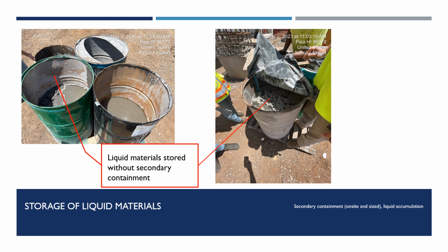Storage of liquid materials requires secondary containment measures to capture any leaks, drips, or potential failures of the container. Secondary containment measures may be plastic prefabricated spill pallets or properly sized waterproof containers. When secondary containment BMPs are functioning correctly, there may be liquid accumulation in the bottom of the container. Although the secondary containment measure served its purpose in containing spilled liquid material, the liquid accumulation must be cleaned out to provide the full capacity for future potential spills.